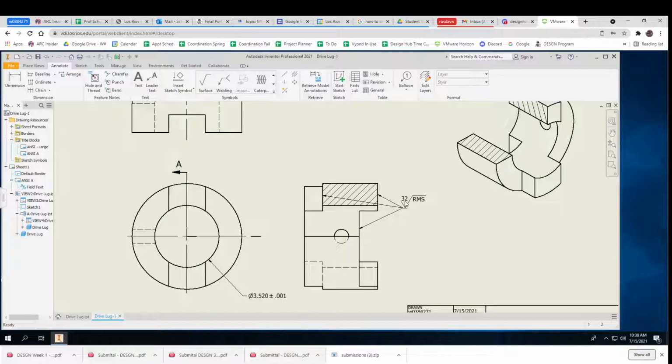So usually people will have a little machining key, a little thing that has those surface finishes that you can look at and see and feel. A 32 is pretty good.